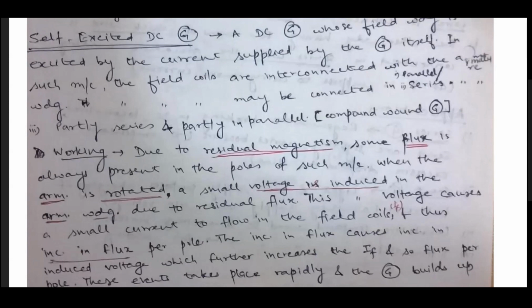this magnetic field system is energized, and now these field coils are connected to the armature coils. Once the DC generator is excited, the external source can be disconnected. There is no need for that setup any further. So when the field coil is there, flux is produced, and due to the rotation of the armature, flux cutting occurs, EMF is produced, then armature current is produced.